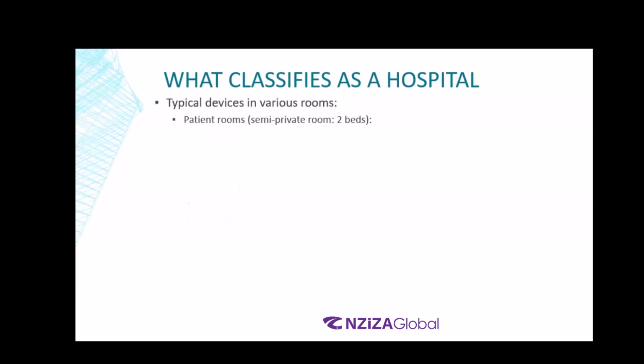Going to the next one, which is the semi-private. Basically talking about 2 beds in one room. Semi-private, right? In between they will have a curtain. In this case, again, receptacles per bed, 2+2, normal plus UPS.